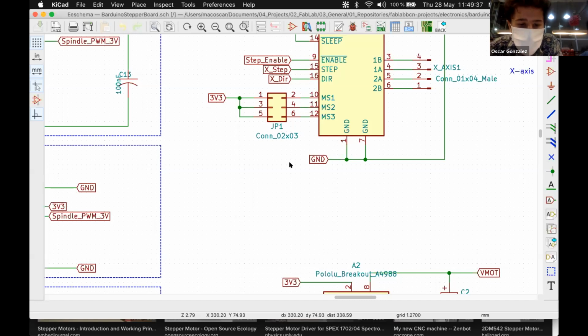And thank you. I don't know if Daniel, that was the question, but these pins are inside the breakout board on the stepper driver, and we don't have to do anything else, just bringing them up to 3.3. It's an internal configuration that the stepper driver works like that internally, but we don't waste a pin on the Arduino to do that.